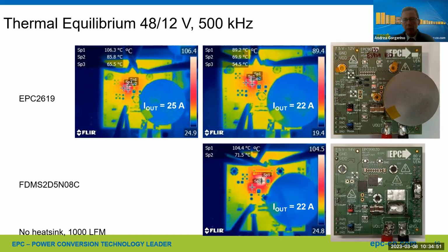However, what is really contributing to EMI are other factors also. So one of them, for example, is reverse recovery. Reverse recovery is a very large contributor to EMI because it's basically a large current that is happening at every switching event, and it's a shoot-through event. It goes from the high side and the low side at the same time. So we don't have reverse recovery. So that's one thing that you don't have.